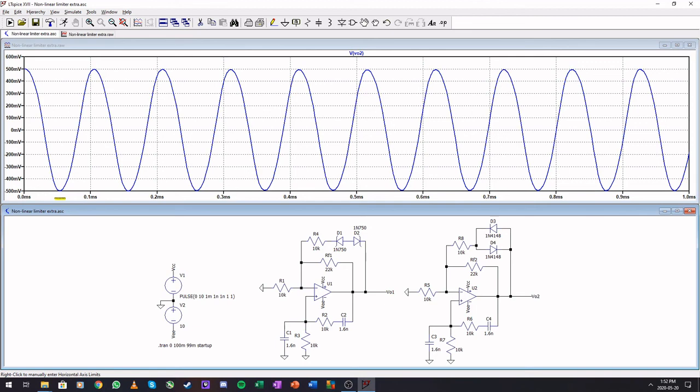We only see the linear-ish part of our transistor's current curve past 0.7 volts. But the diode is on long before that. And this is making use of the non-linearity of our diodes, which starts at more or less 0.5 volts.